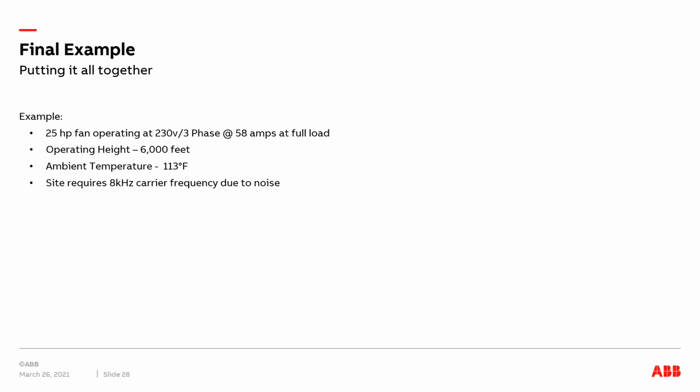The drive that is running this fan is installed in an area that has an ambient temperature of 113 degrees Fahrenheit. Due to the location where this fan is, the job site is requiring that the drive have an output carrier frequency of 8 kilohertz due to noise.